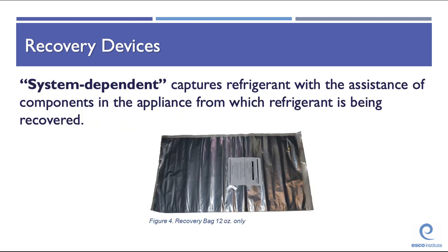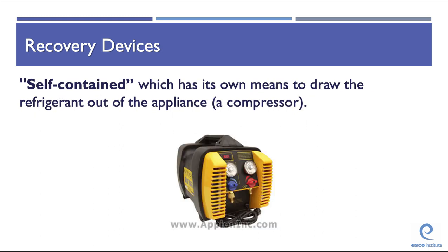System-dependent captures refrigerant with the assistance of the components in the appliance from which the refrigerant is being recovered. In other words, the compressor has to be working. Self-contained, okay, has its own means to draw the refrigerant out of the appliance. In other words, it has a compressor internally to it.